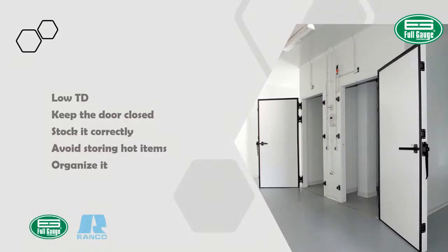A low TD is normally between 8 and 10 degrees Fahrenheit. And there are a few conditions that can help to achieve such a low temperature difference. Some of those conditions are a large evaporator surface, a fully active evaporator, rapid and fast air circulation, and a frost-free surface. These conditions will promote slow frost buildup, high suction pressure, high capacity, and efficiency.